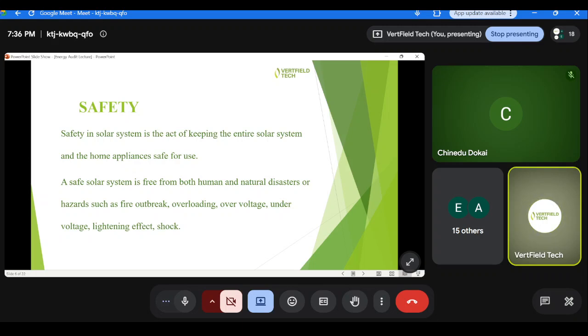In some installations, I don't know if you've seen some of the videos, when some installers finish doing their job, doing a very good job, and they put their tester on the body of the inverter system, you will see that the inverter system has current. Yes, that means that there is a problem with that system. That system is not safe enough to be operated.